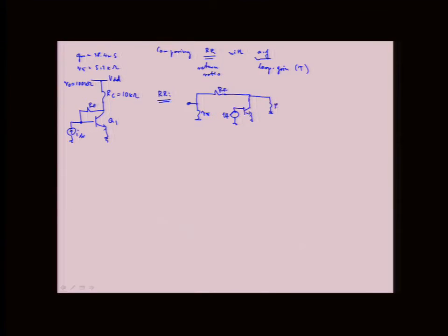And then I'll just pull RC and RO out of the transistor. So we can say from here that return ratio is, so this will be VR. And then we're opening this because the input is a current source, right? So that's a simple schematic for return ratio.